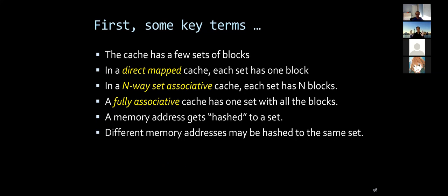Well, when I say very small, still bigger than registers, but a small subset of the data that we believe can be used in the near future. So instead of going to memory and paying, I don't know, 300 cycles, we store it in some smaller SRAM-based storage. It's going to be slower than registers, but it's something on the order of 4 to 10 cycles, right? So that small thing is something we put in the processor itself.